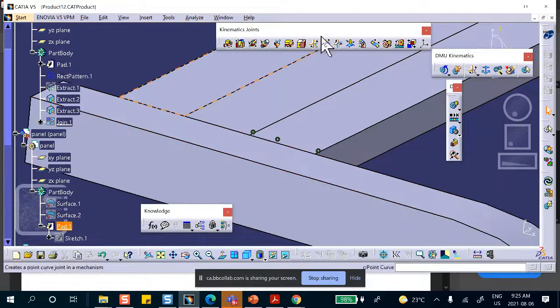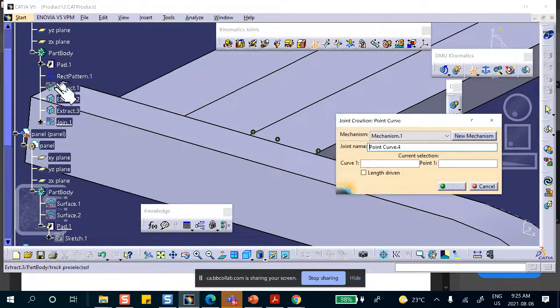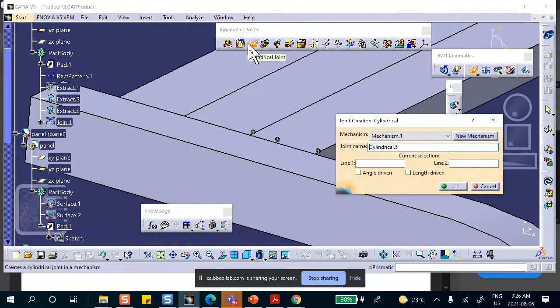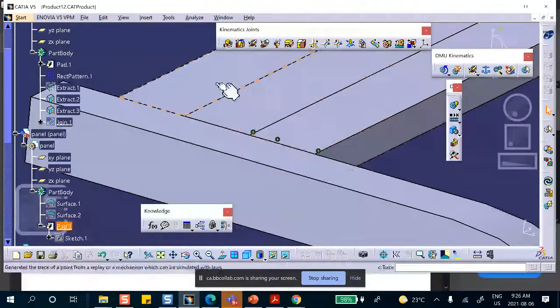And another one between that joint that I had and this point. Okay, good. Now, these are cylindrical joints, okay, because these are hinged together. So coincidence, not coincidence, cylindrical joint. Now, the problem is which one, see, they're sitting on top of each other and hiding, unfortunately. Okay, you know what we can do? We can do the following. Separate these apart temporarily.